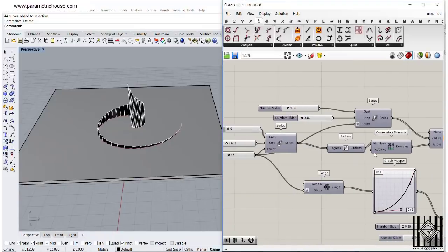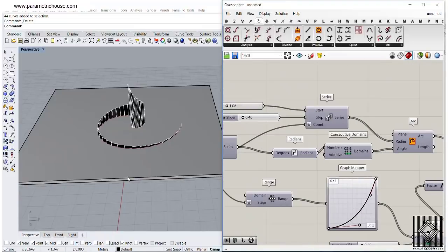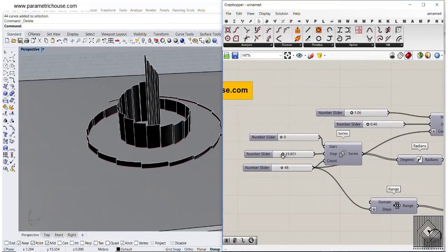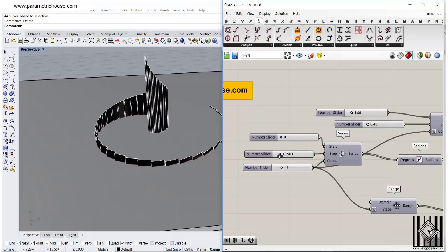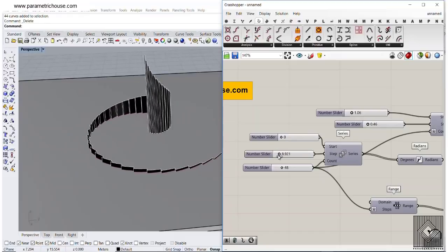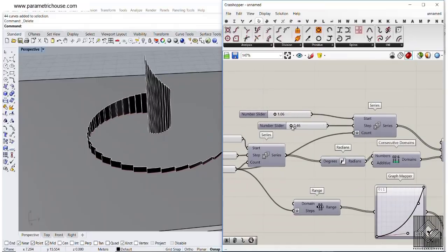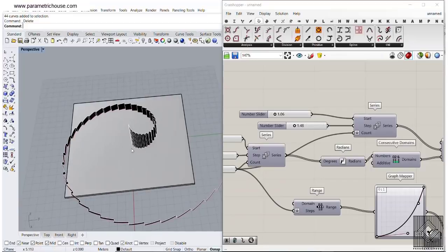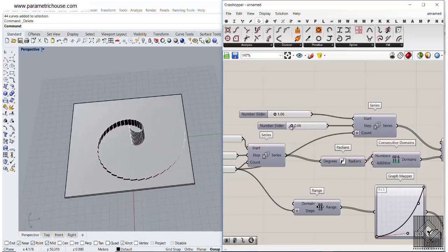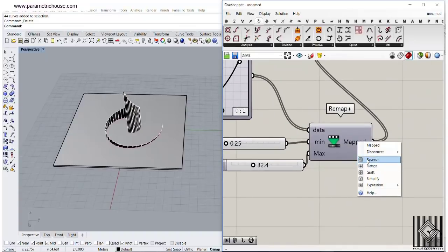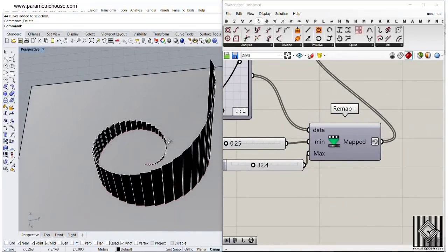In this Grasshopper tutorial, I want to show you how you can use the arc tool to produce a parametric surface, something like this, where we can change these parameters. As you can see, we can make this a more rotating curve like this one, increase the height, and change this one. This will just make this bigger or smaller, and change the start, and also change the minimum and the maximum of the height, which we can simply also reverse to produce something like this.